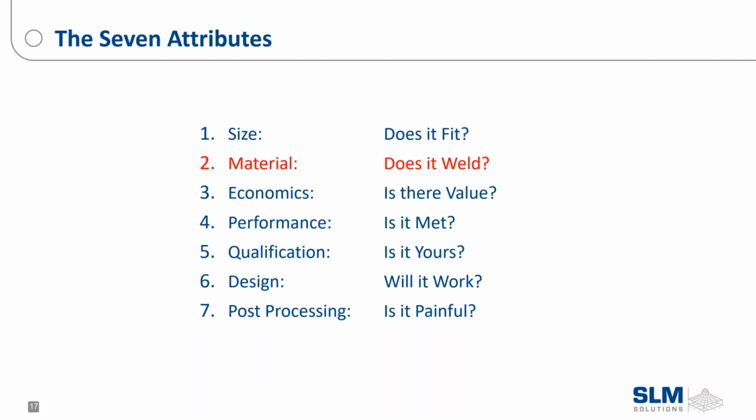This is lost area, so your part may actually be 280 millimeters, and it might not fit onto a build plate based on geometry and positioning of the part. So when we say 280 by 280, yes, the build cylinder is 280 millimeters by 280 millimeters, but there are some smaller tolerances and, of course, the bolt holes here that we need to take into consideration when placing a part.